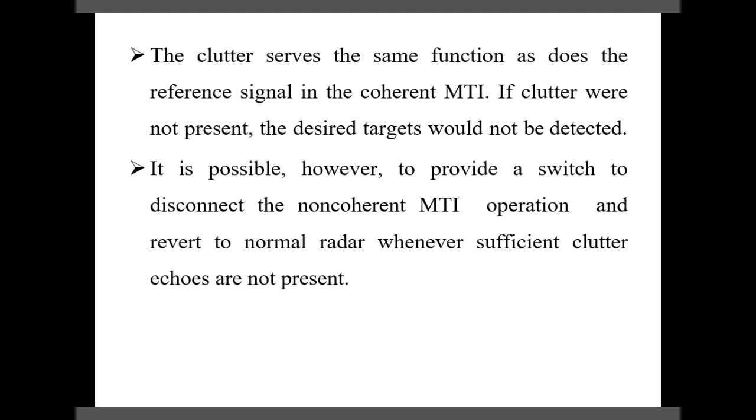It is possible, however, to provide a switch to disconnect the non-coherent MTI operation and revert to the normal radar whenever sufficient clutter echoes are not present, because it can detect the target within the clutter only. So we can provide such a system that we can switch between coherent and non-coherent operation.